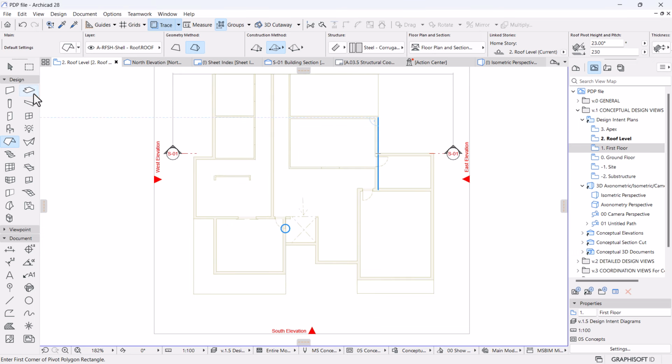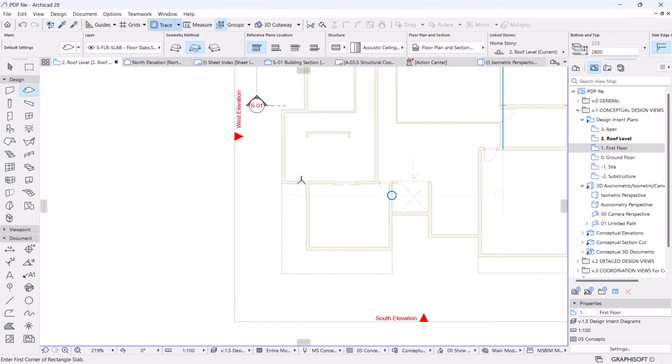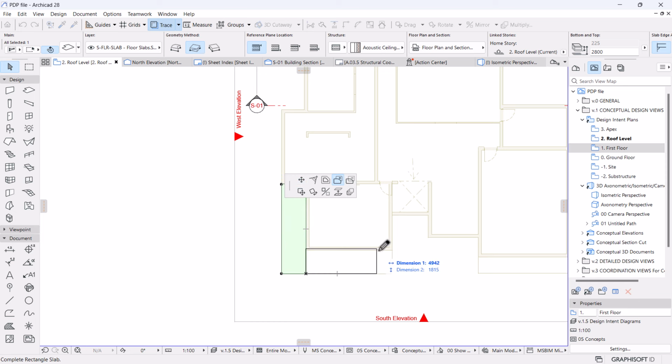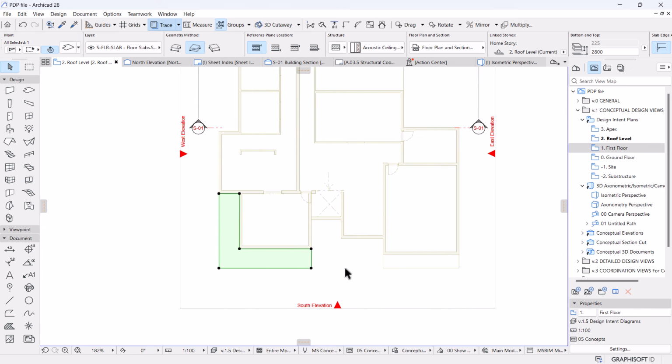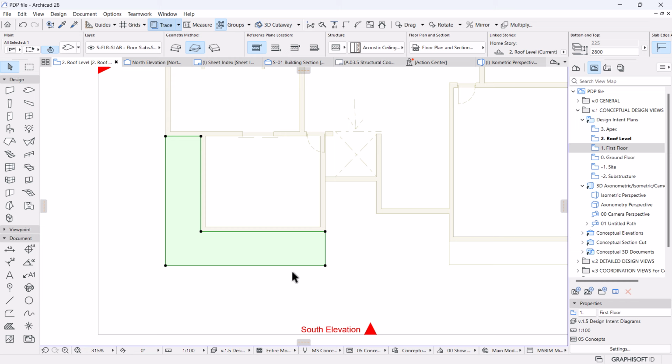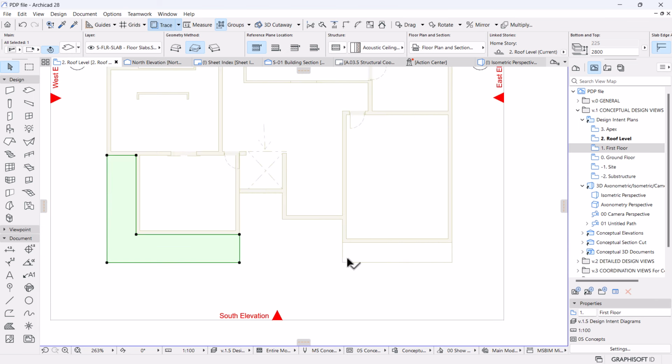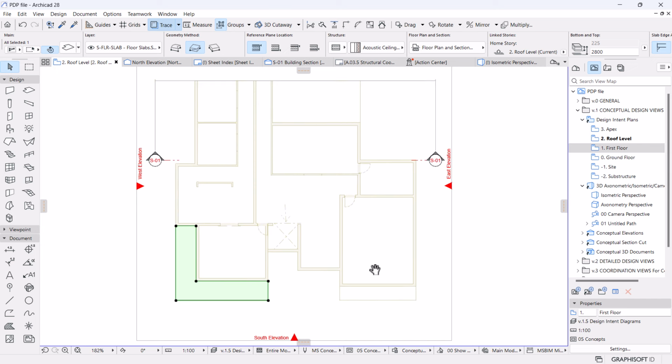All right, let's activate a slab. I'm going to start with the portions that I'm having a roof slab, like this part, and let me add a polygon to stretch it all the way to there. I'm going to get rid of this point because it's unnecessary. For best practice modeling, to assemble a well-resolved model, you need to get rid of these points because they add up to the file size. And ultimately the file will start crashing due to this.